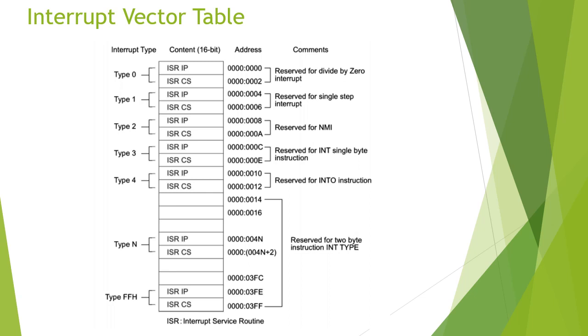A special program called the interrupt service routine takes control of the CPU to a data structure called the interrupt vector table, which is stored from the beginning of memory, marked by segment 0000 with an offset of 0000. Whenever the CPU receives an interrupt type number, it is multiplied by 4, and that gives the offset of the procedure which can handle that interrupt type.